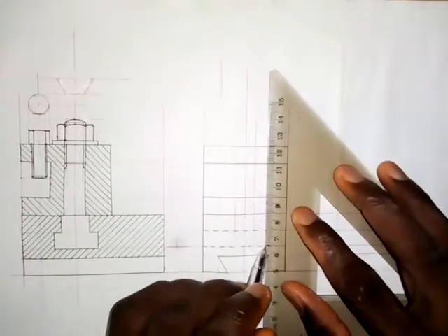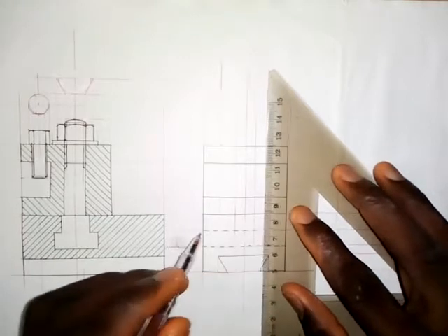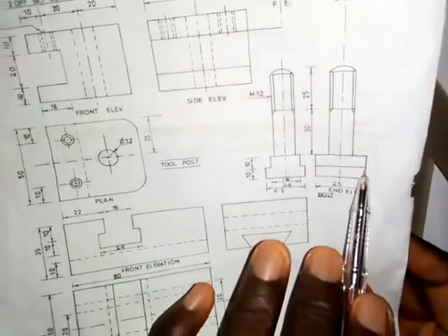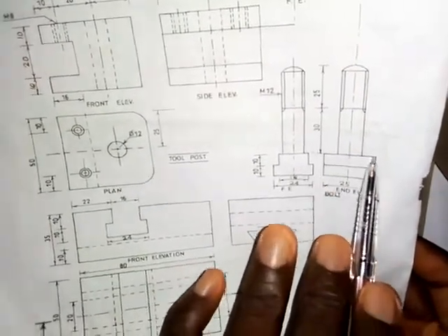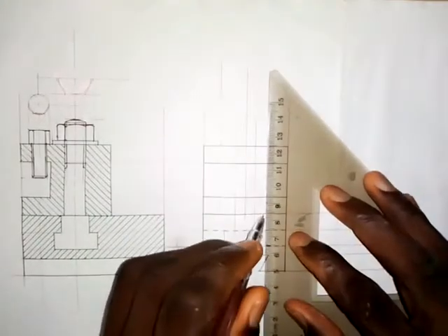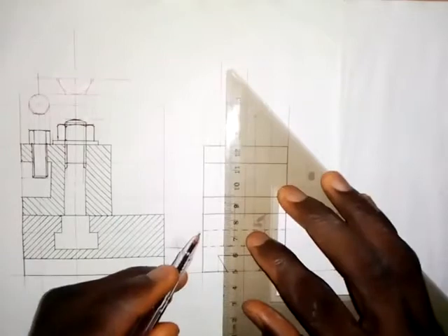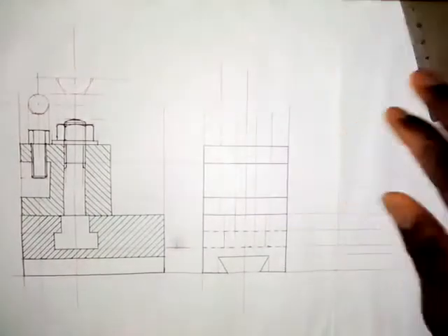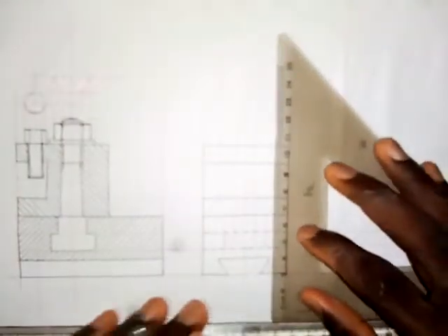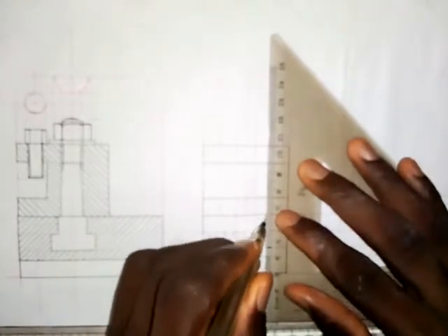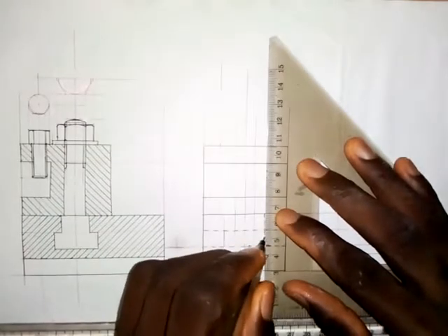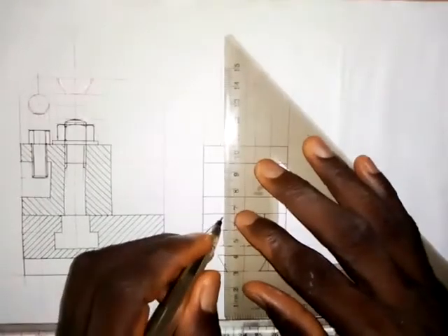We draw the vertical line. So we draw a vertical line here. Draw a vertical line here. And then if you look at this now, if this goes up to this place, it is still that 25 millimeters. So I will still produce it to this level here. It is going to be hidden from me. When I'm looking at it from outside, it will be hidden. So we are going to draw this as a short dashes line. If I'm looking at it in this direction, I will not see it, so it will be hidden from me. That's why we have to make it a short dashes line.